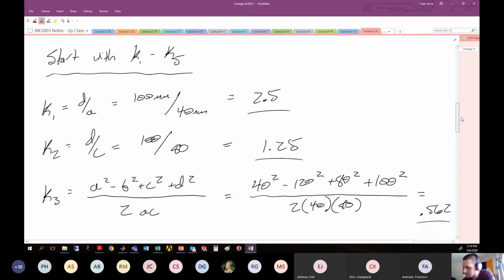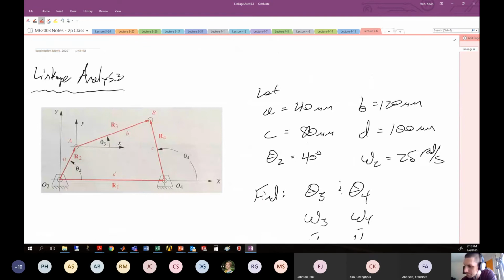What I mean by that is, if we go back up to our model here, here's our value of theta 4. If it's negative 98 degrees, that means it's down to roughly about here. So that link is in this configuration for negative 98 degrees. So it's likely that this is going to be some crossed configuration. Opposing that is the 57.3 degree entry, which maybe looks something like this.